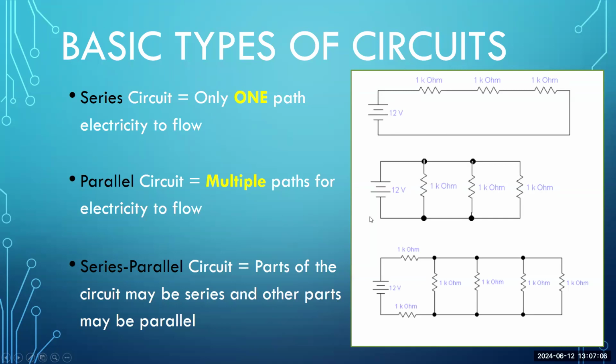If you look at my illustration on the right, you'll see the same DC voltage source. You'll see the positive plate, which is the long plate on top, and the negative plate, the short plate on the bottom, and electrons are said to flow from the negative plate down to the right. And as soon as it hits this dot, we call this dot a node. A node is a connection point in schematics, as well as a connection point on your boards when you build things. And at this particular node, the current will split. Part of this will be divided to come up through this load resistor, and part of this will continue on this wire to the other ones.